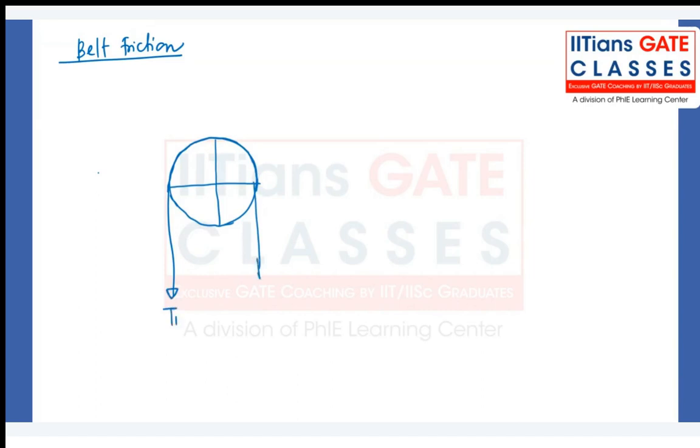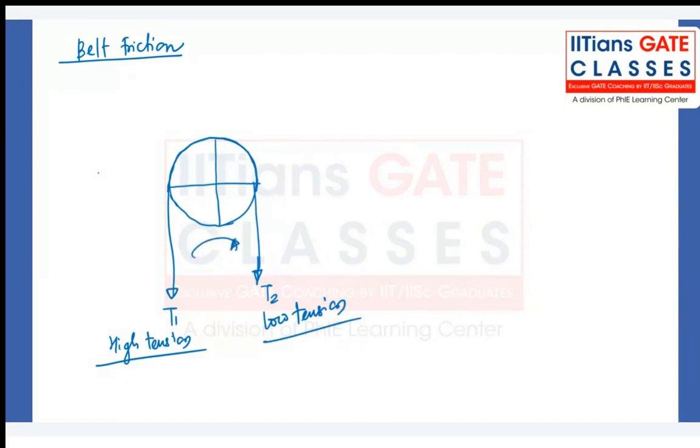How to find T1 and T2? T1 is, let's say, the high tension side, and T2 the low tension side. If this pulley is rotating in the counterclockwise direction, the arrow indicates the high tension side. If it is rotating in the clockwise direction, then the arrow will indicate the high tension side. So whichever direction it rotates, that side is higher. Assume here it is rotating in the counterclockwise direction, so T1 is the high tension side and T2 is the low tension side.